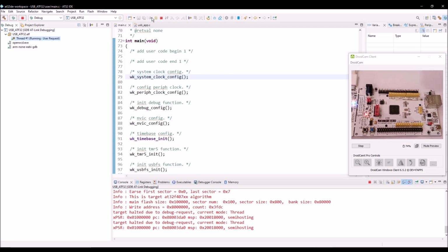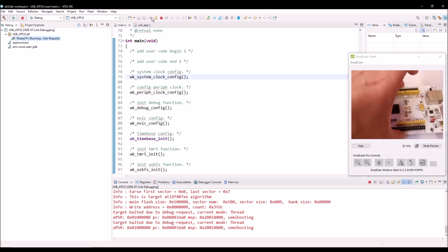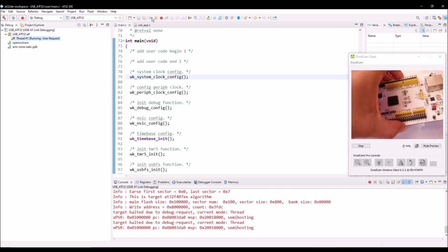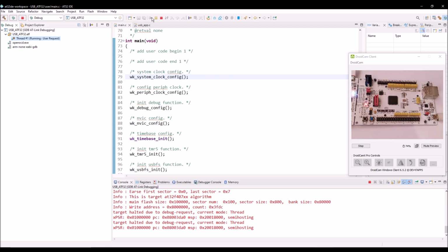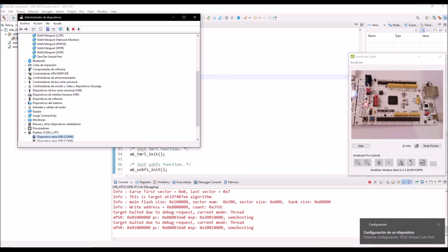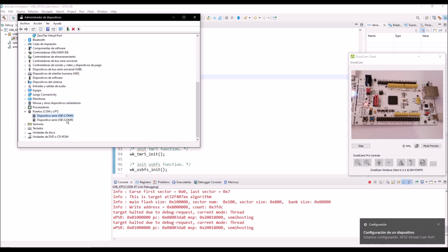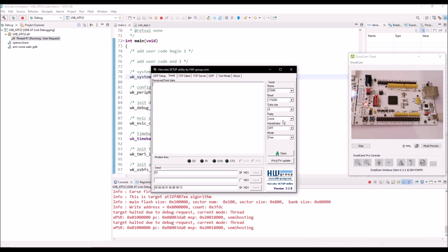Then, I go to the development board to connect the USB cable to the corresponding port, which is near the bottom right corner. Then I open the device manager to determine the COM number assigned to the hardware, and it's number 9. Also, Windows notifies me that it has detected the hardware and is configuring the device. Using the Hercules software, I open COM port 9 and proceed to send the number 1.